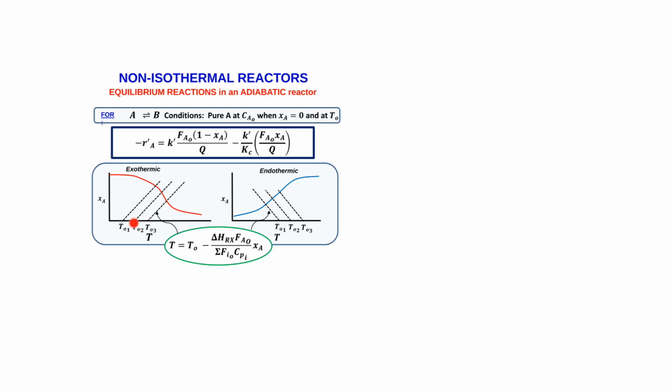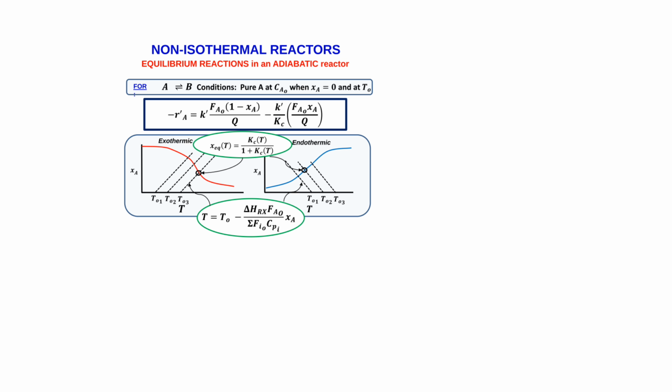If you start decreasing your inlet temperature, that maximum equilibrium conversion is going to increase for an exothermic reactor. I can observe the same kind of behavior in an endothermic reactor, but here as I increase the temperature, adiabatic operation, so therefore of course the slope is going to be negative over here, and I can see for an infinitely large reactor, this is the absolute maximum conversion that is possible, whether you have a CSTR or a plug flow reactor.